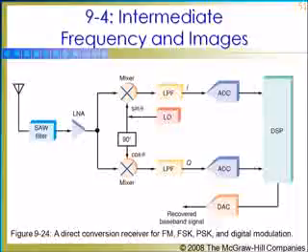The upper signal is usually referred to as the in-phase, that with letter I, signal, while the lower signal is referred to as quadrature signal or the Q. The I and Q signals are then sent to analog to digital converters, these two ADCs, where they are converted to binary signal.